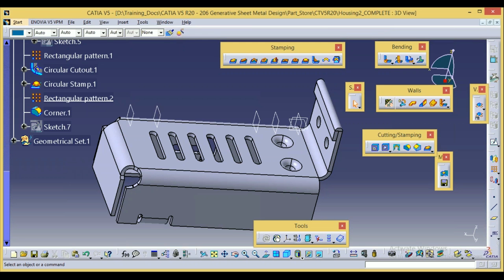But for bending there are different types of bendings again. This V bend is to achieve normal bends. Depending on the angle we can fix the angle and achieve 40, 50, 60, 70 to 90 degree bends, or 120 degree bends.